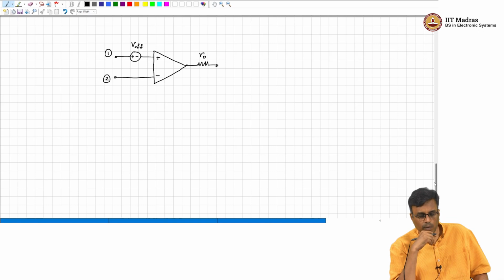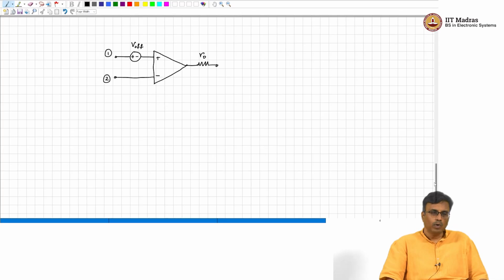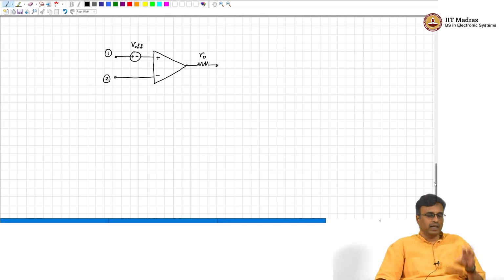If you have an op amp with finite output resistance, what comment can we make about the output resistance of amplifiers we use? We take the op amp and build an amplifier, isn't it? Before we actually do the analysis, what should we expect when we take this op amp and put it inside a feedback loop? Earlier we said that the output resistance of, say, a voltage controlled voltage source or the inverting amplifier or the non-inverting amplifier was 0, correct.